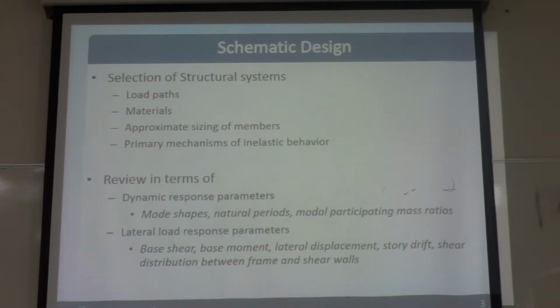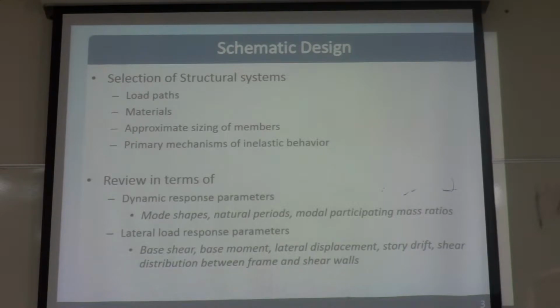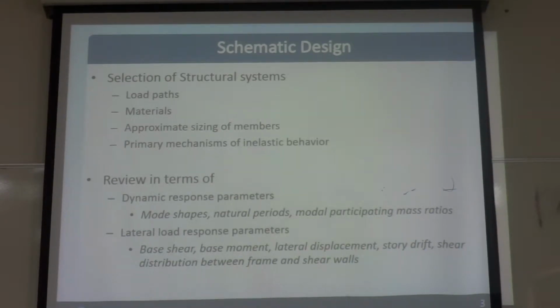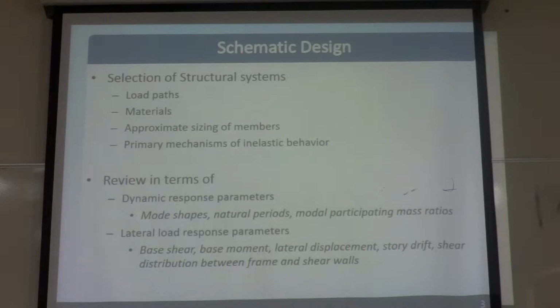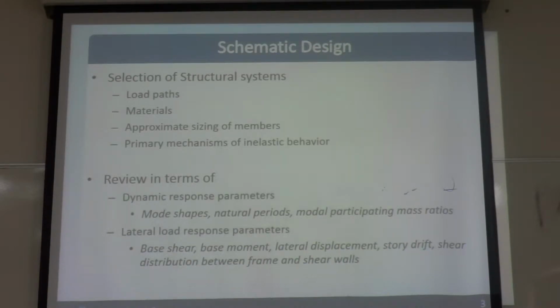That is important. If we do not do the schematic design properly, and we continue the detailed design, we will have a lot of problems in the detailed design stage. When you calculate the reinforcement at the detailed design stage, the forces cannot be manageable. Sometimes when we check the required reinforcement, the reinforcement is too high because we do not develop the proper structural system.